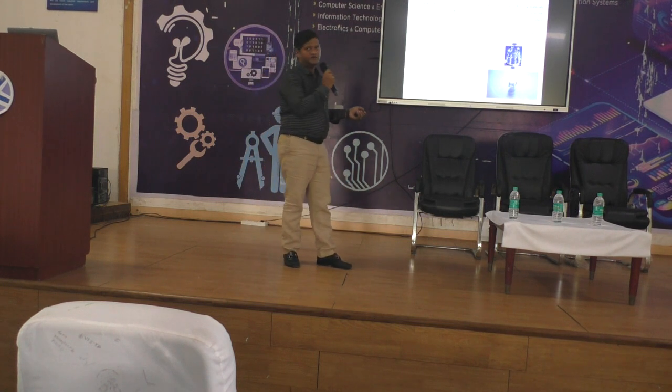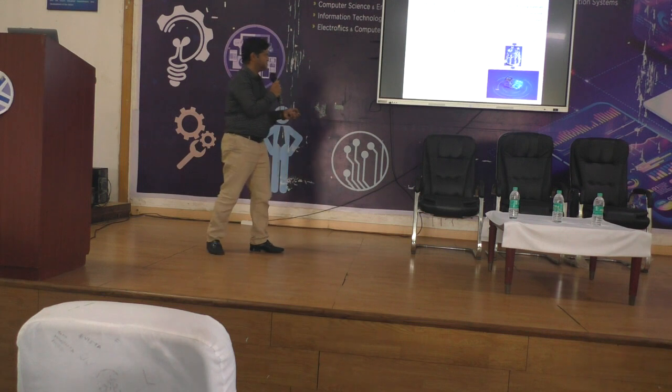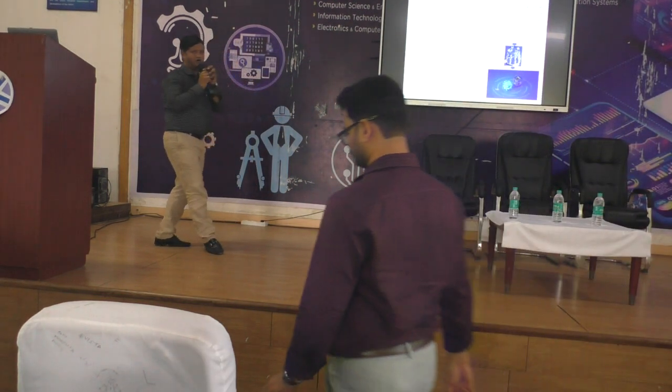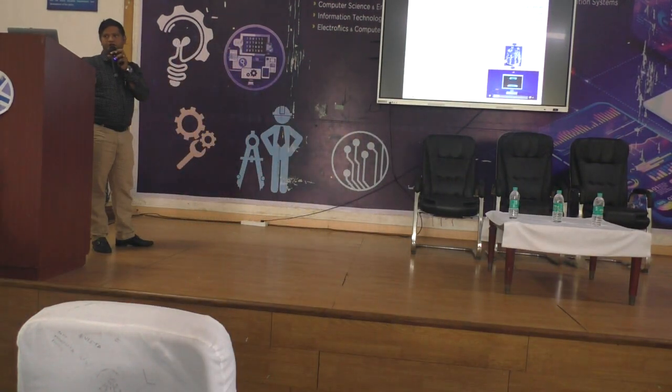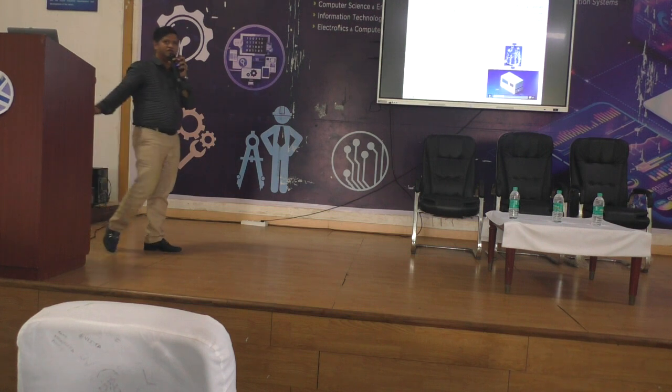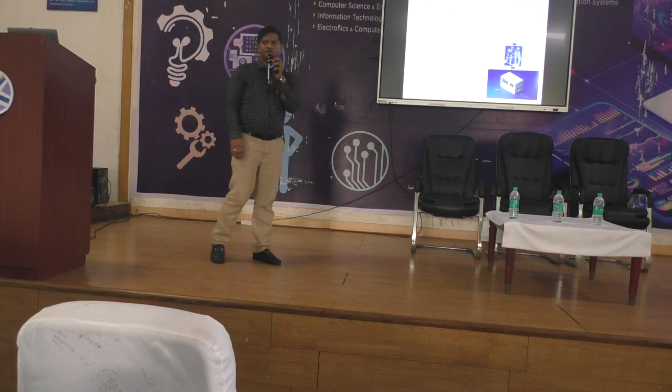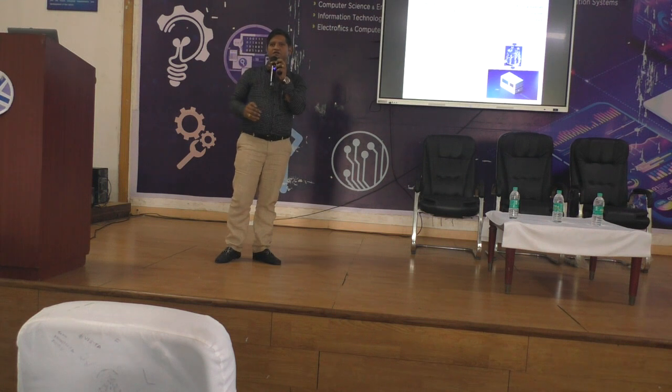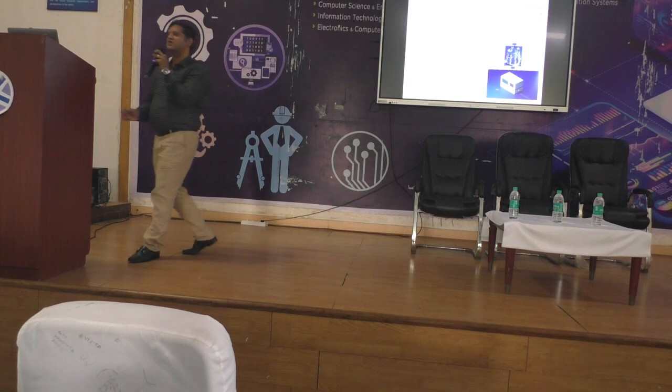It starts with a CAD model, the digital replica corresponding to this component. And then we slice this CAD model or the STL file. For each slice, we generate the path programming, and this path programming, or the coordinates information of each slice, will be communicated to the machine,